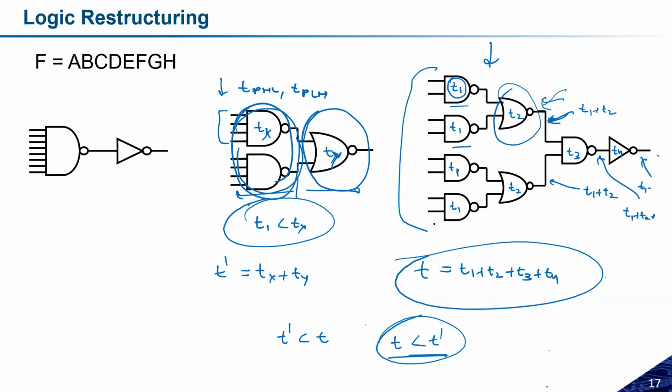Might be the third structure, whatever I just told you, could not be the effective one, because this gate delay will start dominating the internal delays. So you cannot optimize the propagation delay. You have to find an optimum way in which you can design your circuit. Yeah, so this is really very important.